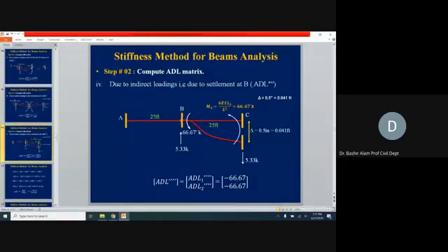So this is now the situation. Look, A and B are clamped at the original position, but here at C we are sliding it down by 0.5 inch. Now because of the settlement, it will try to go back, 6EI delta over L squared. This is actually C, this is not A, this is MC. So these are slight corrections. Faisal is there, so he should be realizing these mistakes now. So this is C now.